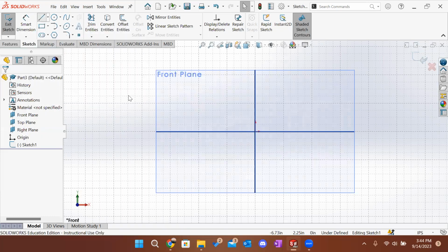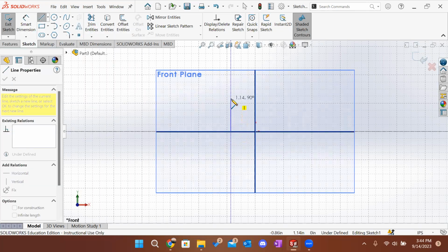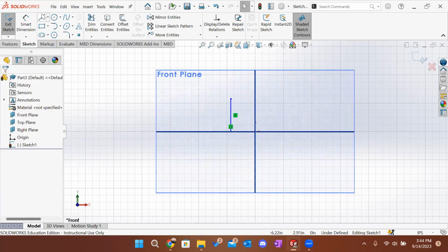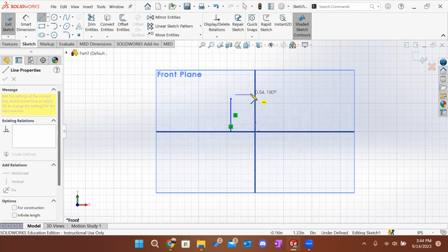now I'm going to make a line here. I'm going to hit escape, and I'm going to make a second line, but let's say instead of having it associated to this little orange square that pops up, or the yellow square, let's say I don't start from that point and I just start over here. And I make a line like this. And then I connect them over here.